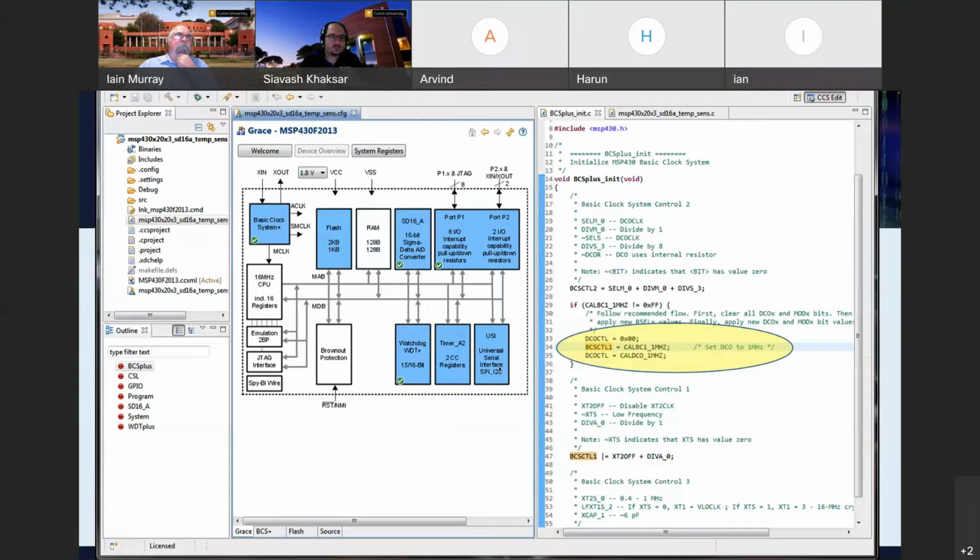With that sort of setup, you need to interrupt the current normal flow of your program. To do that, you need to hold the current state of your program somewhere and go somewhere else to handle a subroutine. In this case, this would be an interrupt, and then go back to the infinite loop cycle. All of this requires very low level, critical management of the code, because you don't want to be in a situation where you have interrupted the program but are not able to go back to its original state.